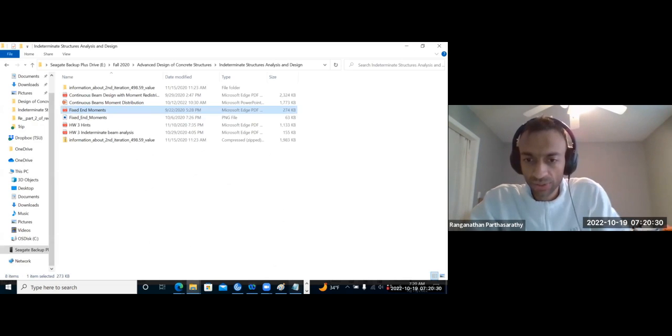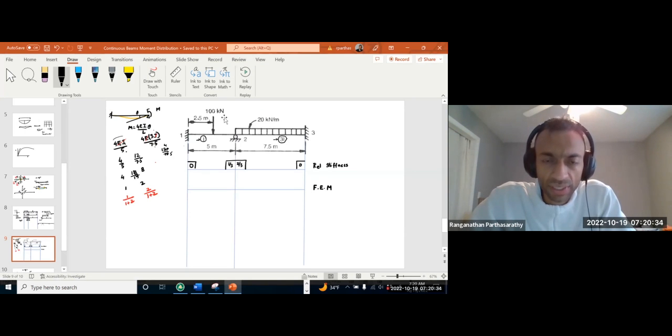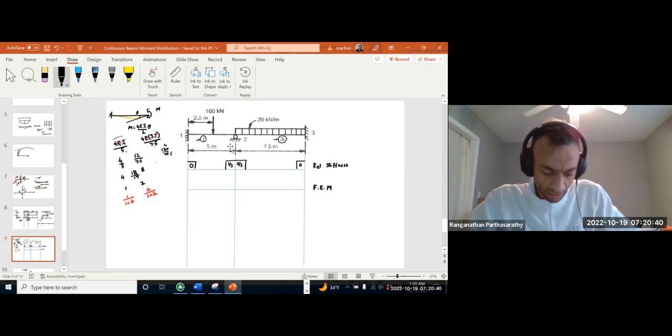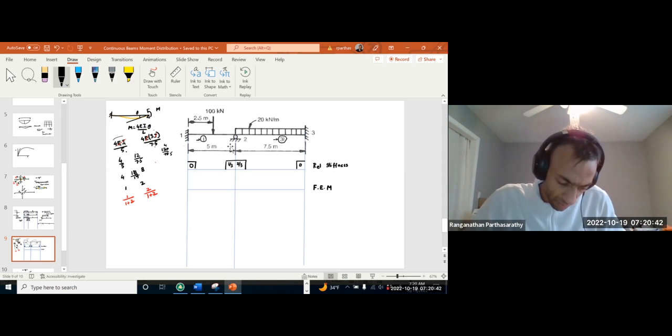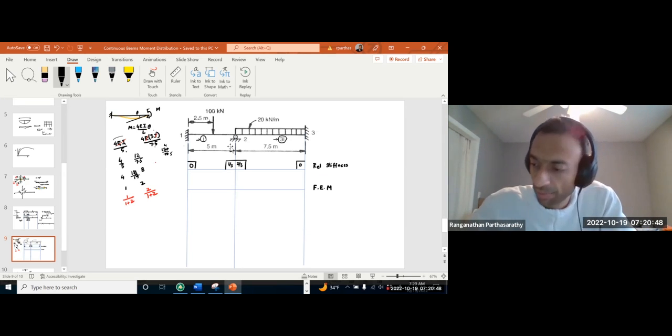So let's use that. P is 100 kilonewton, L is 5 meter. So we have PL by 8, 62.5 kilonewton meter. So let's put that.